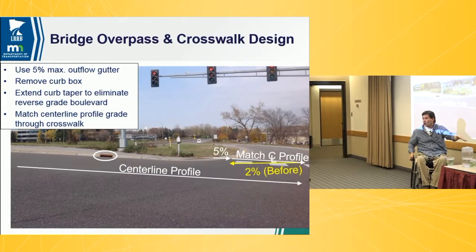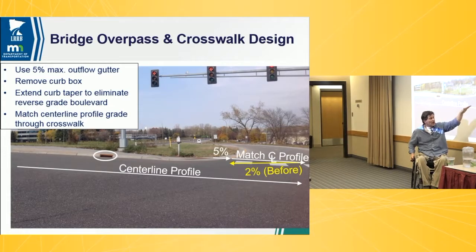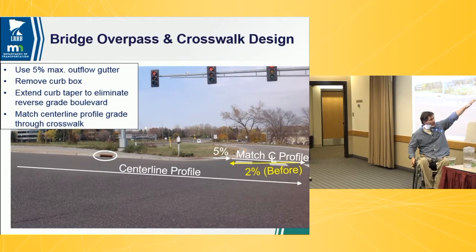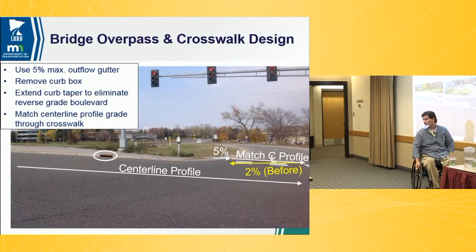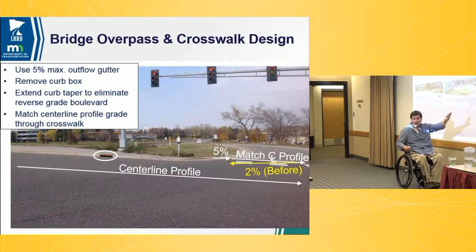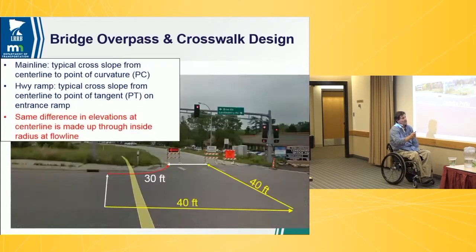I just put that curb ramp in a little bit of a hole just because I want to maintain this typical section. This road should theoretically come in at the same cross slope right here, or we hold our profile for our center line right through our crosswalks. Do all your crowning and supering after you get outside of the crosswalk. So that's one thing where these corners get hard, because we want to fight grades with our typicals.